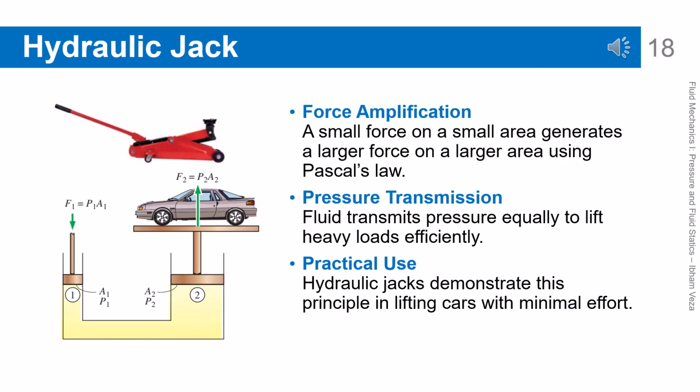Hydraulic jack principle. This principle is based on Pascal's law, which states that pressure is transmitted equally in all directions. A small force acting on a small piston can produce a large force on a bigger piston. This relation follows F1 over A1 equals F2 over A2. With this principle, heavy loads, such as cars, can be lifted using relatively small forces. Hydraulic systems are widely used in industrial and automotive equipment.